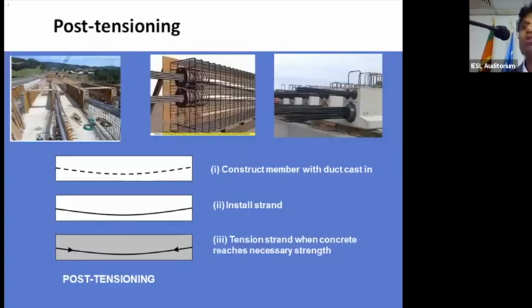What is post-tension? Post-tension gives the designers the option to lay the tendon profile the way you want it, right? Because if you look at the bending moment diagram, you can lay your cables along that line so that you can get more benefit. I think the beauty is that, with post-tension or pre-tension, the understanding and advancement of high-strength concrete as well as high-strength tendons give us these bridges. We'll come back to it a little bit later.